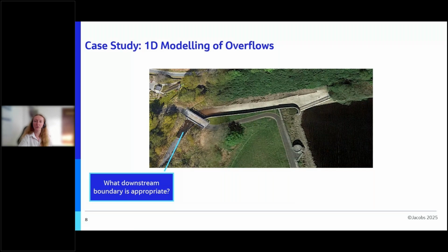So a location was identified on the chute where the channel suddenly goes really steep. At some point, flows will move from subcritical to supercritical at this sudden change in gradient, and so we can assume we go through the critical depth around here. Therefore, the model was set up with an FM critical depth boundary downstream of some surveyed cross-sections of the spillway, which you can see here.